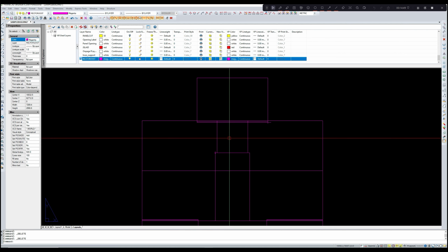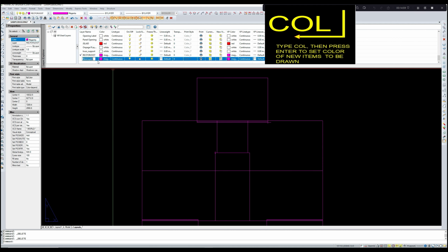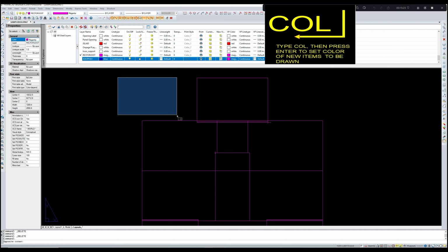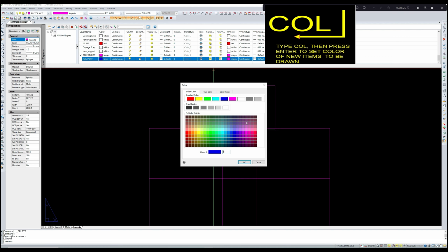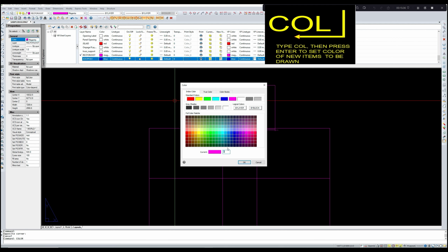Now we'll draw some closed polygon. These polygons are required for drawing the joist. So let us make another layer, new layer, joist poly. Let us make the color blue. Okay. This is also blue, color number 5. Set the color as 5.